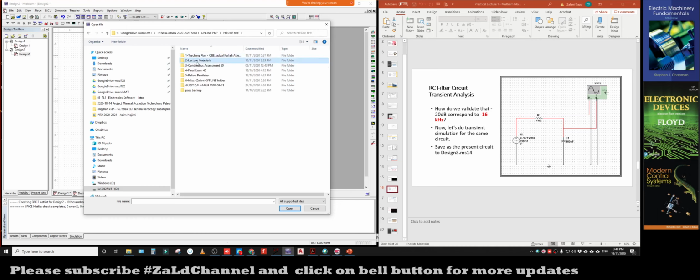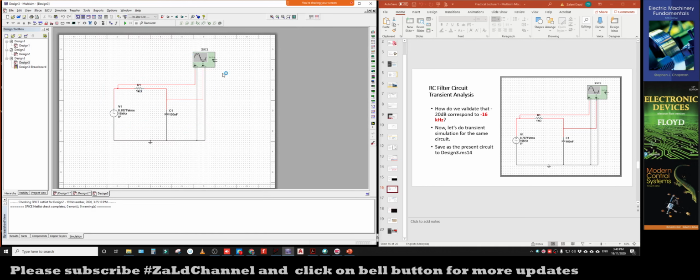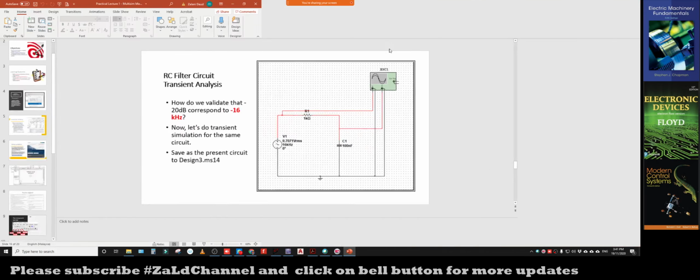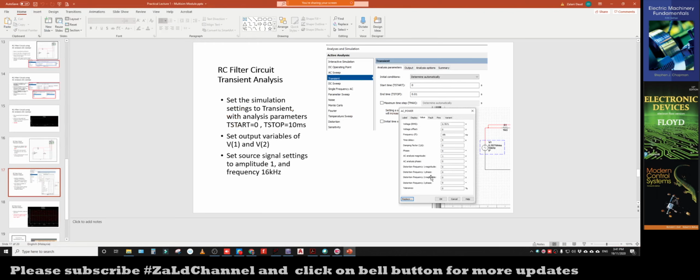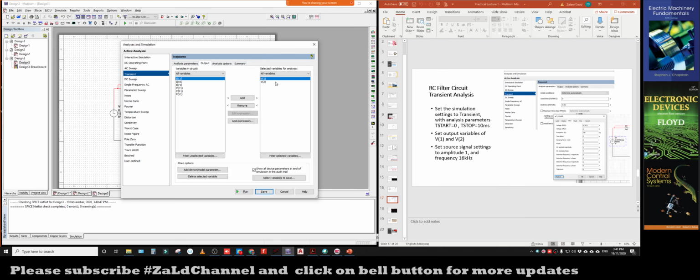We use the same circuit, but we adjust the simulation analysis setting. We change this from AC sweep to transient. We set the simulation from 0 to 0.01, which is 10 milliseconds, so the transient analysis will start from 0 to about 10 milliseconds. We still measure the same output, which is V1 and V2.